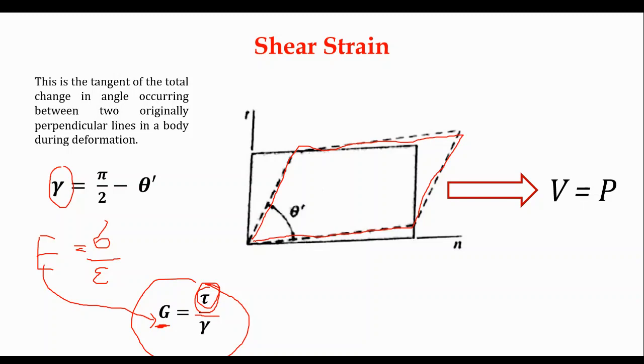So what objects have a small G? For example, rubber. With rubber, if you just pull or push it, it deforms right away, so it has weak resistance to shearing strain. But with steel, even if you push it you will not see it deform, its surface stays intact. Then, how do we relate the modulus of rigidity to the modulus of elasticity?